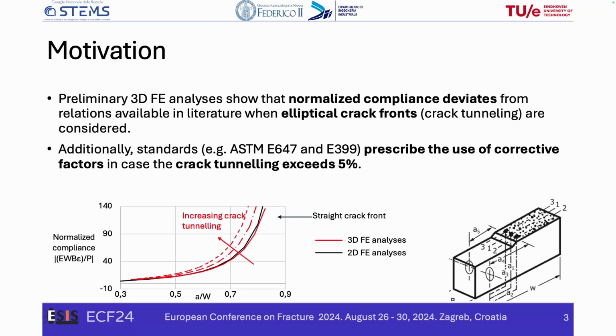However, preliminary 3D FE analysis in our study revealed that normalized compliance evaluated based on measurement at the backface deviates when crack tunneling occurs. Crack tunneling is the term for the occurrence of elliptical crack fronts or non-straight crack fronts.